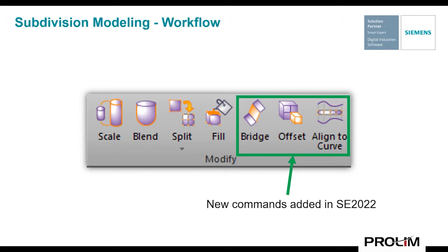As you create and as you edit, you can use symmetric mode to make subsequent local changes symmetric about the user-defined plane. Using the Pathfinder in subdivision modeling, you can convert a subdivision body into a design body by selecting the Toggle Design Construction command on the shortcut menu. Then you just close the subdivision modeling to exit the environment, and you're back in your traditional sheet metal or part environment.